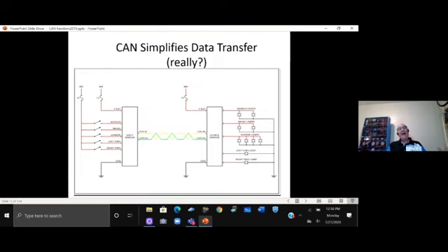So now with that in mind, as this becomes simpler, say that this output module is in the door and all the various functions are right there. What do we have to do? We have to communicate to it. So what does it need? It needs power, it needs ground, and it needs signal. If it has power and ground and signal, then the input module on your left can communicate with the output module on the right.